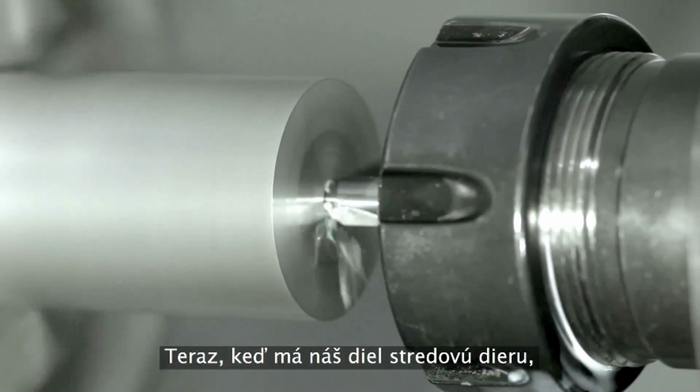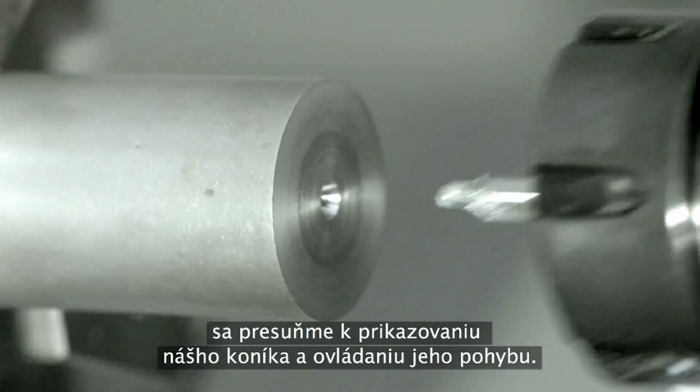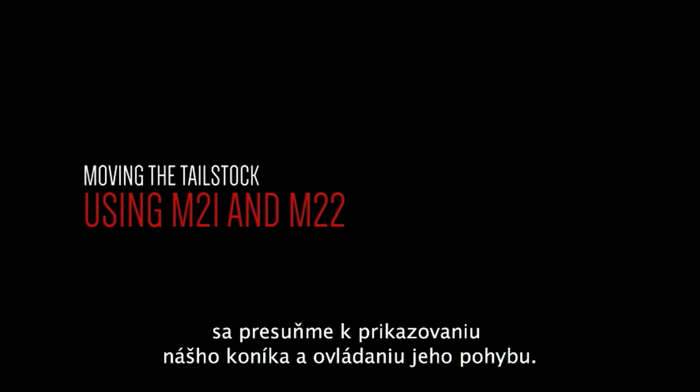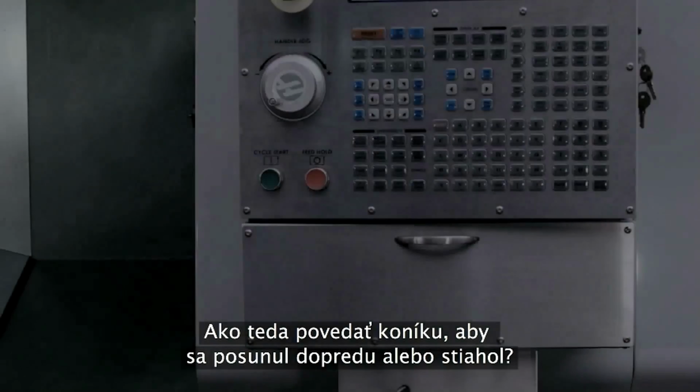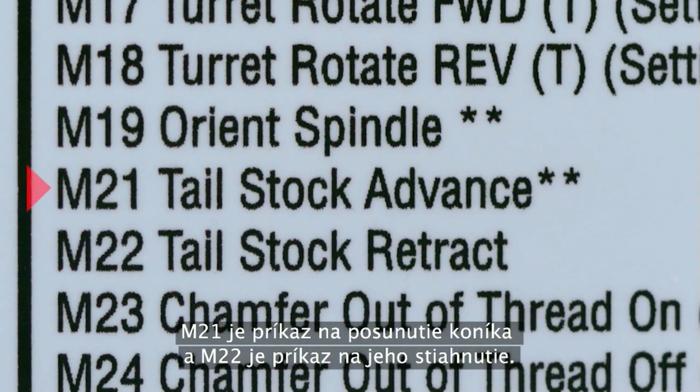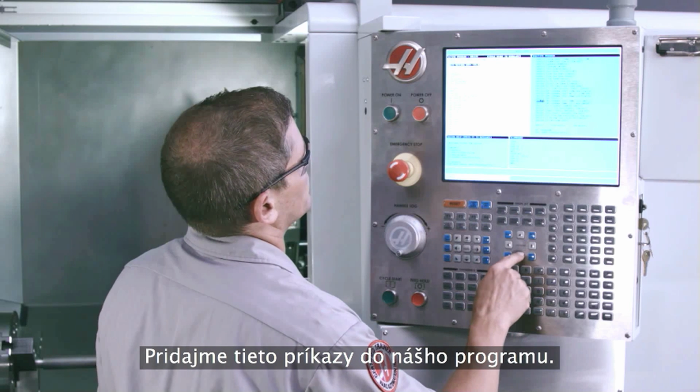Now that our part has a center hole, let's move on to how we command our tailstock and control where it moves. So how would you tell the tailstock to move forward and retract? M21 is the tailstock advance command, and M22 is the tailstock retract command. Let's add these commands to our program.